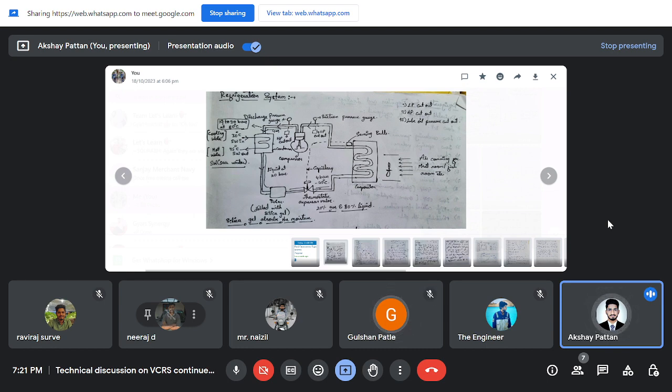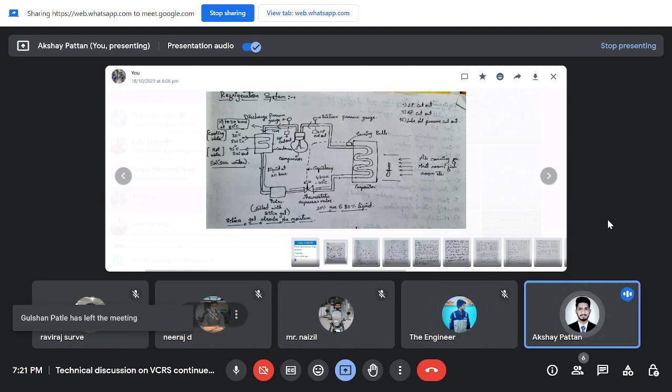Okay, due to this flow resistance, the crankcase is continuously going into friction and wear and tear. So to avoid this, the lube oil needs to be heated to flow smoothly into the crankcase, right? That's why the oil heater is used as a safety device inside the compressor. It is fixed inside the compressor. Okay, is it clear, guys? Yeah.